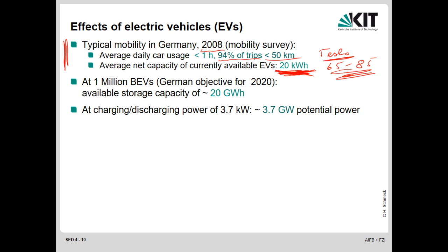But the major point I wanted to mention is that having a larger battery means that you need fewer cycles, and it means that your battery will live longer, because the battery ages with the number of cycles to some extent. Since you only have a limited number of cycles that is guaranteed before the capacity goes down by more than 20%, which is normally the limit that you would tolerate, it's just a better approach to have larger batteries.